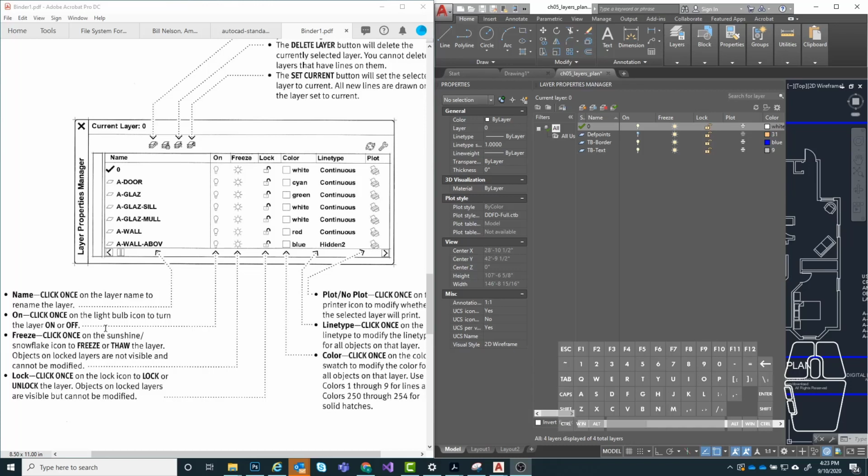Okay, but basically it's a way to control which layers are on and off on a per drawing basis. The regular light bulb just does it universally throughout the entire project. If I click off here it's just going to be off everywhere in my drawings. But then the freeze and thaw, it's going to control it based on the drawing layout that I'm currently looking at. So that'll make more sense, like I said, later on. But just keep in mind the difference between them.